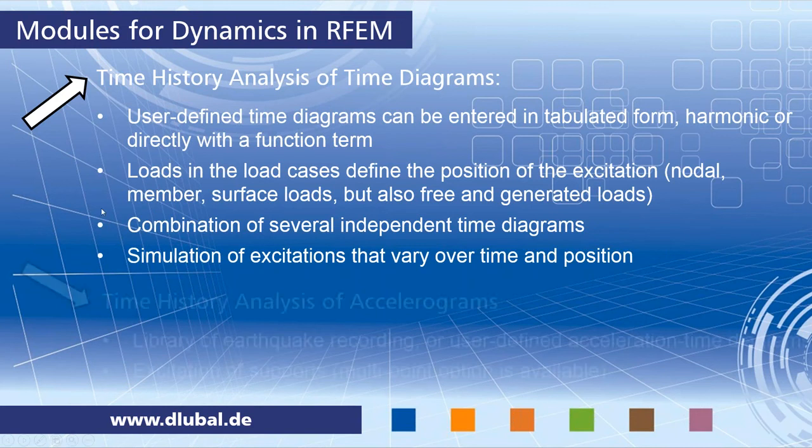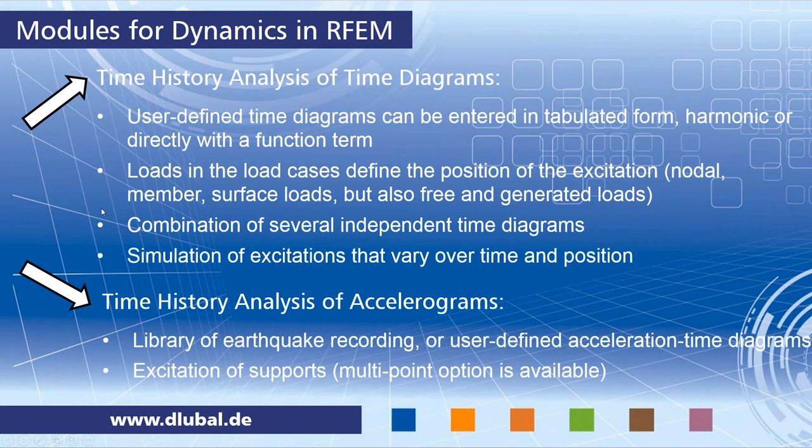The second option we have available is a time history analysis of oscillograms. You can either choose an earthquake recording from our library, or you can define the acceleration time diagram yourself, or import it from Excel. Here you have an excitation of supports. This is not a free excitation somewhere in the structure. It is an excitation of supports, but we have the multi-point option available. This is similar to the response spectrum analysis.